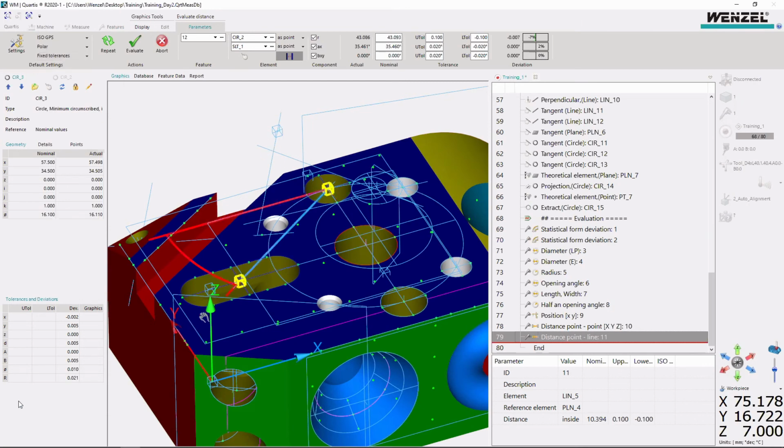Then we will have our R, angle alpha, and angle beta. Angle beta is 0, because right now both of them are on the same projection plane. So the shortest distance that I need is this, the blue color one, which is the R. These two I don't need. And then the R will be 49.086, which is the actual value. And then the upper and lower tolerance.